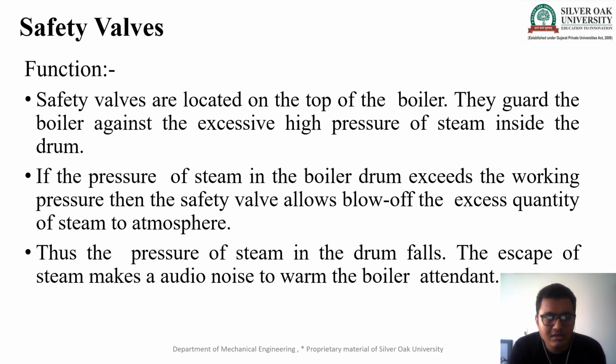If the pressure of the steam in the boiler drum exceeds the working pressure, that means if I have a boiler whose working pressure range is 70 bar to 100 bar, then there is no problem. If the boiler pressure goes above 100 bar, then it will be in danger.